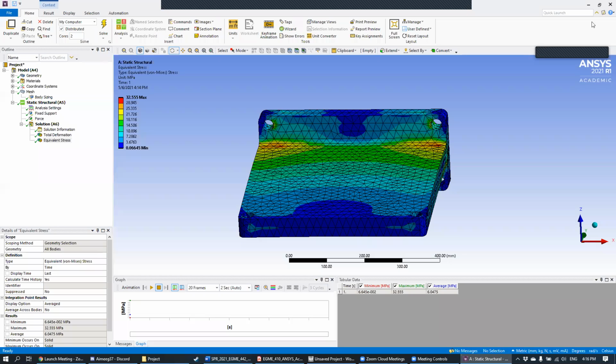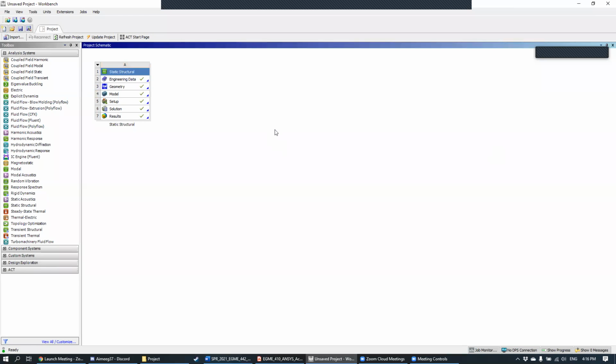Let's go ahead and close Ansys Mechanical, right? Okay. It's going to bring us back to Workbench, right? Our static structural analysis is complete, and our boundary conditions and simulation results are good. Okay. What we have to do from here is launch another analysis type, okay? I think this will be the first time that we're doing this. And then we need to link the results of this static structural to the topology optimization, okay?